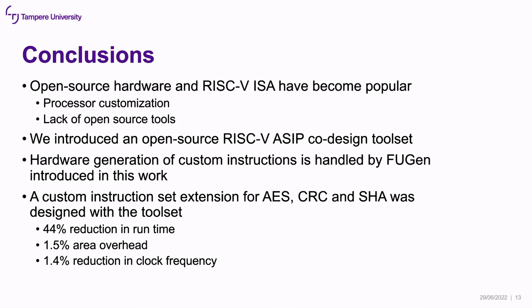As a design case study, we created a custom instruction set extension for the AES, CRC and SHA applications. The extension reduced runtime by 44% on average, increased the area only by 1.5%, and reduced the clock frequency by only 1.4%.